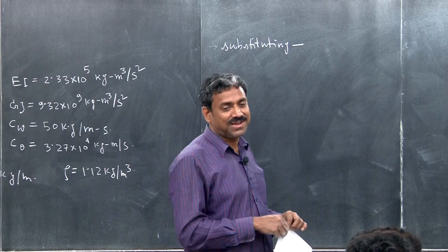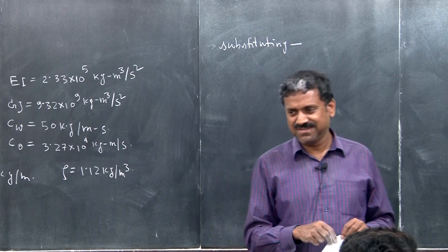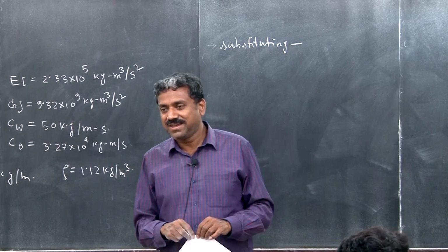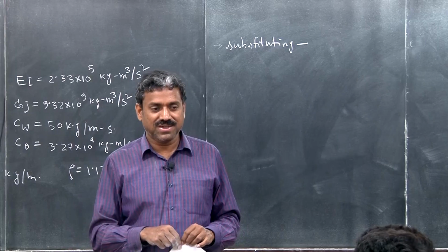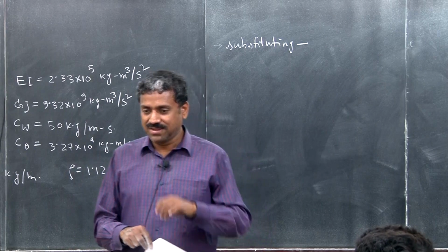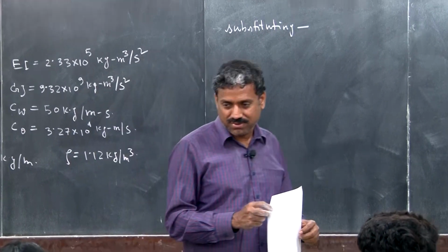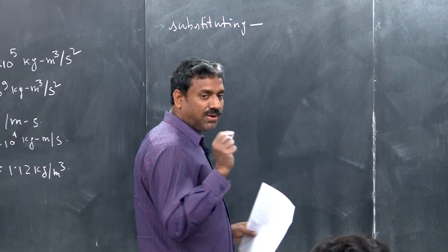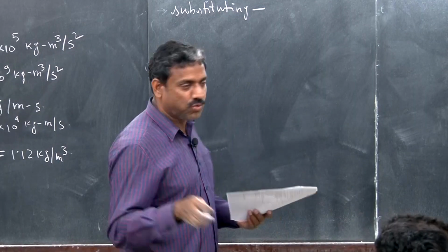But it's a quadratic eigenvalue problem, so you will get 4 natural frequencies. But yes, the imaginary parts will be identical. Understand that? Otherwise there would be 4 lambda values, right? Anyway, you can associate them with the 2 modes.